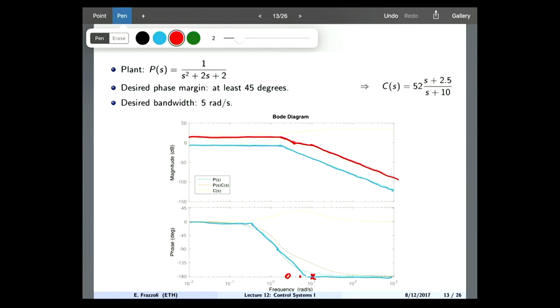So where was I? One way you can look at it is that I know the geometric mean must be 5. So I just need to multiply 5 by some number, let's say 2, and divide 5 by the same number, 2, to get the pole and zero. I can choose that number to be 10, or 20, or I can choose the number to be smaller. Keep in mind that the smaller it is, the less of a phase lead I will get. The larger it is, the closer to 90 I will get. In this case, do I need the pole and zero to be that much separated? Not really, because I don't need 90 degrees of phase lead. 30 degrees will be fine.